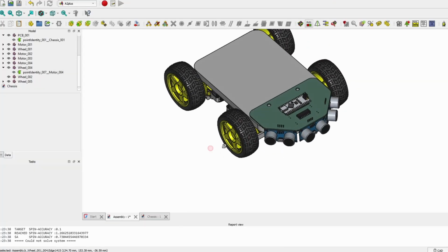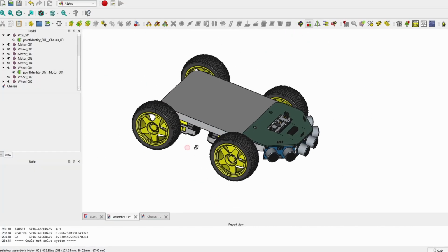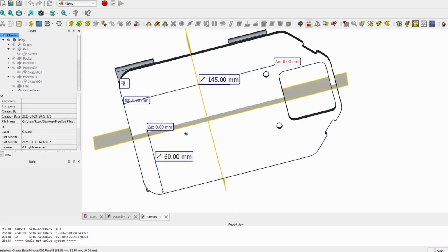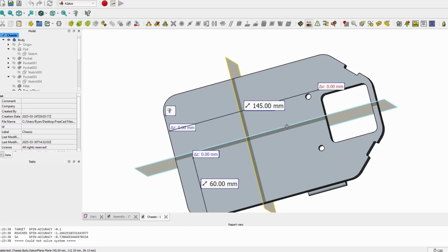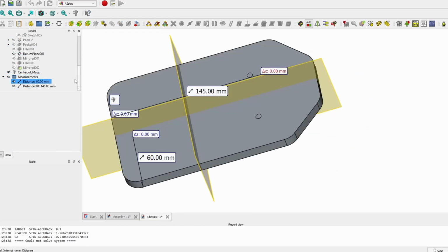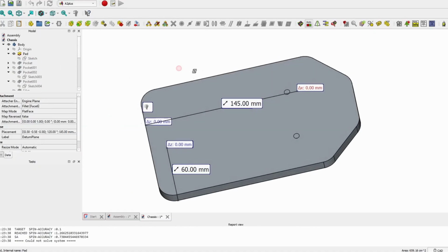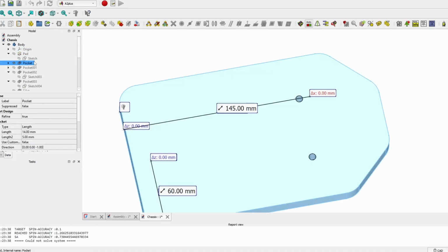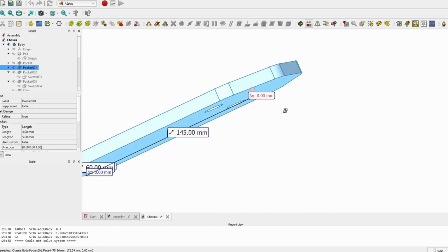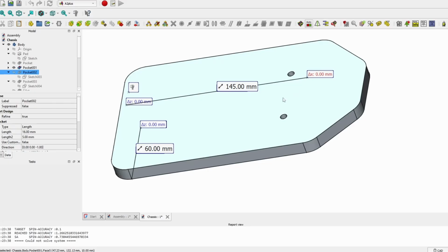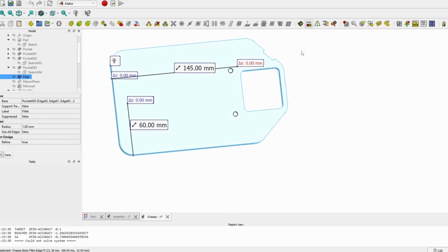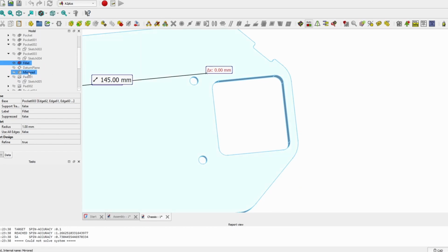Okay, so this is the object avoiding robot, the CAD model of it, the assembly. So if we were to go to the chassis, you could see how I would have drawn this basic shape out from the very beginning. So if we were to go to the pad, it would have been sort of like that. Let me just get rid of all of these other things right here. You can see how it's a pad like this, and then we pocket a sketch. We go down to do that on the other edge, or on the other side. It's for bolt heads and stuff like that. And then we continue to pocket and make changes to this feature, or to this 3D object.